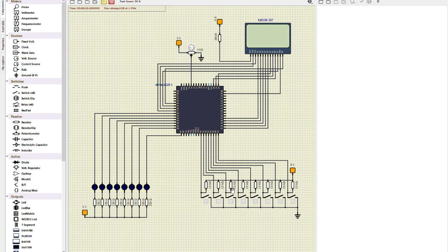So as we remember from the first part, we can clearly see that if we set the ignition on and the door open, we have this lamp here. It's pin 0 on the B port, so we can see the lamp appearing here. We should filter out all of the other cases with the XOR. So if we tap some unrelated button, the lamp turns off, and we cannot use it anymore.